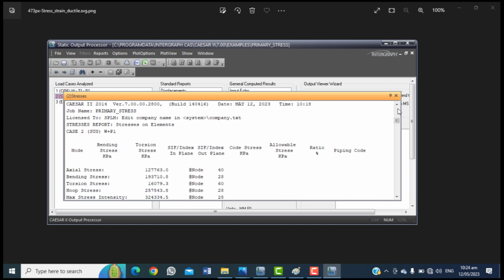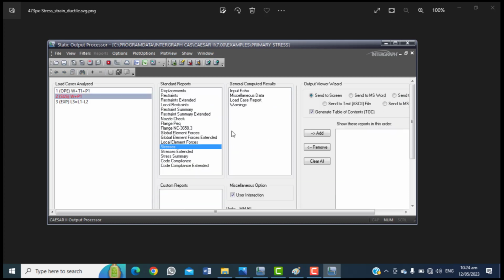257 is already greater than your allowable stress of 125, right? So whenever hoop stress fails the system, it only points to an insufficient thickness, which is insufficient to contain the fluid pressure. So remember when we were doing this design, we started from the least schedule, and we just wanted to exaggerate this to show you that these are the likely things that are going to fail your system.